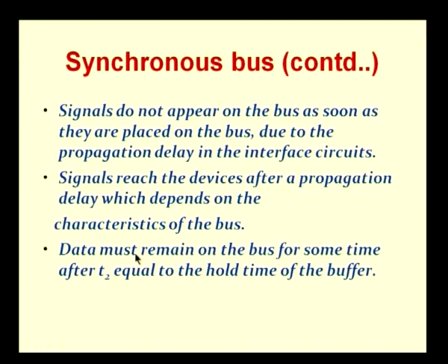So, before it can be placed on the bus, again there will be some delay. Okay. So, both these delays have to be taken into account. And data must, as I said, remain on the bus for some time after T2, which is equal to the hold time of the buffer. So, we have the setup time, which is the time before the clock that it should be there, and some time called the hold time after the clock for which the data should be available. Only then you can make sure that the data is successfully written into the buffer.